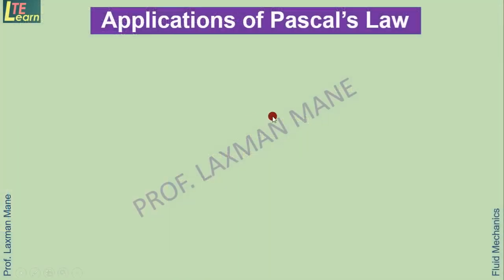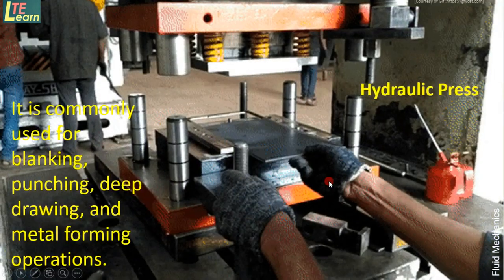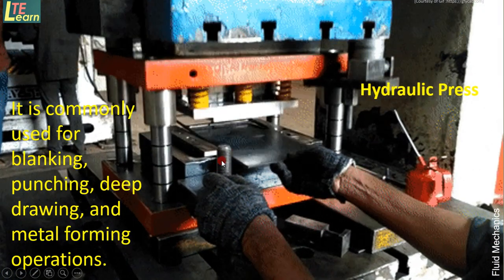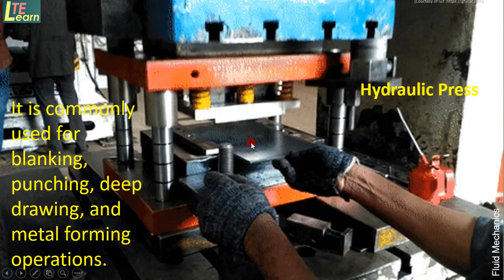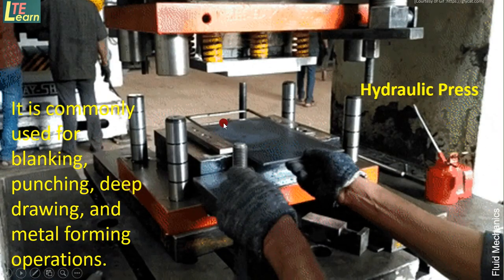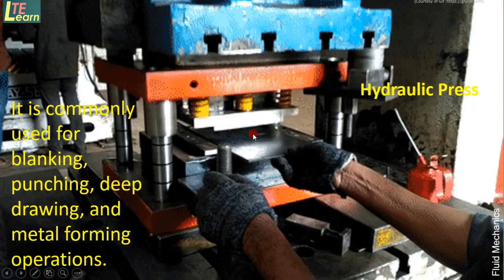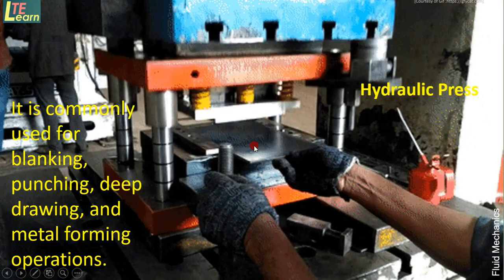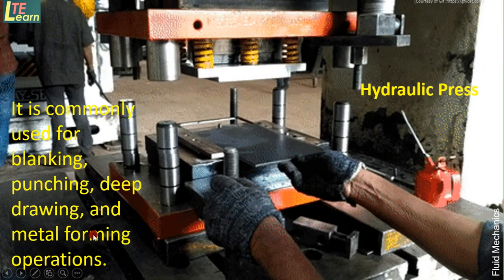Let us see some applications of Pascal's law. Pascal's law is used in the construction of machines such as the hydraulic press, which is commonly used for different operations, that is blanking, that we see here. This is what blanking operation means, making a large hole, rectangular or any kind of shape, in this metallic sheet. The other operations that can be carried out are punching operation, deep drawing and metal forming operations.